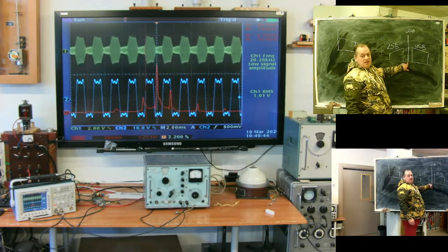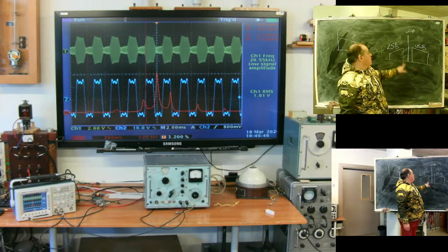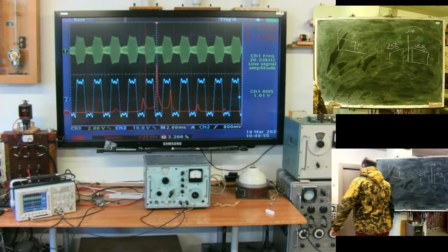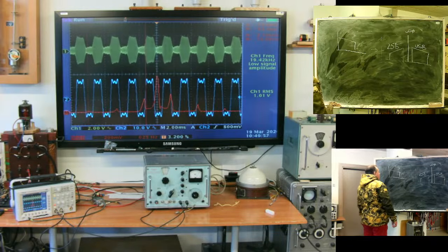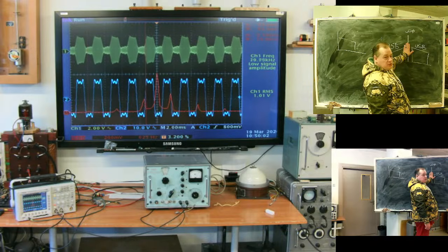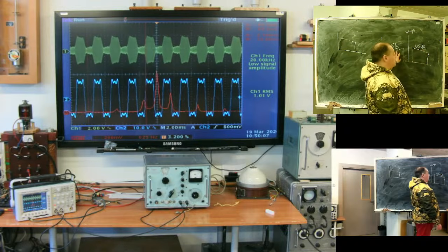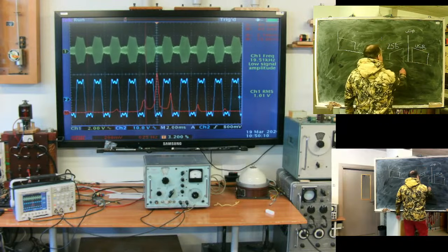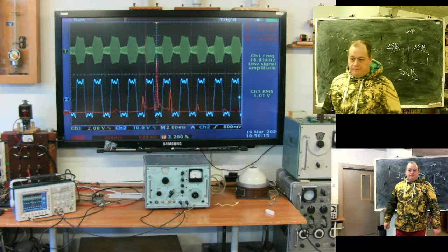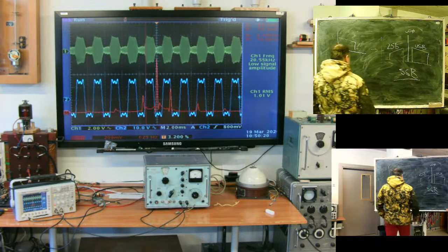Here at the carrier, there is no information, actually it's wasted energy. Both sidebands carry the same information. So, to save energy, this can be rejected from the signal. It will be a balanced modulated signal. Only the upper sideband can be transferred, or only the lower sideband. That is SSB type of transmission. SSB transmission is used for commercial communication.